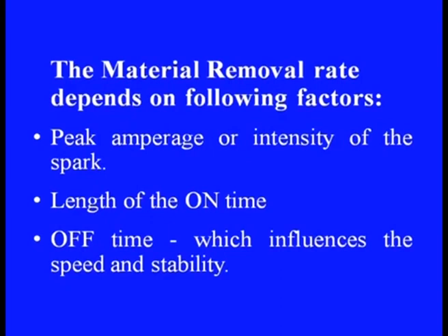The material removal rate depends on the following factors. Number 1, peak amperage or intensity of the spark, the length of the on time, the length of the off time, as I have already indicated, which influence the speed and stability of the sparking. Then the duty cycle.